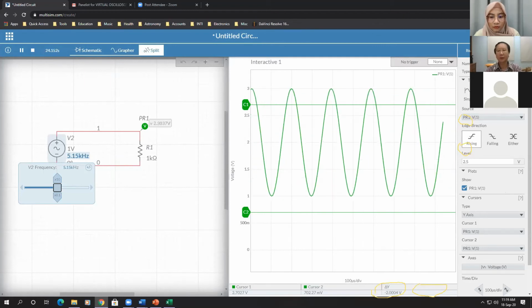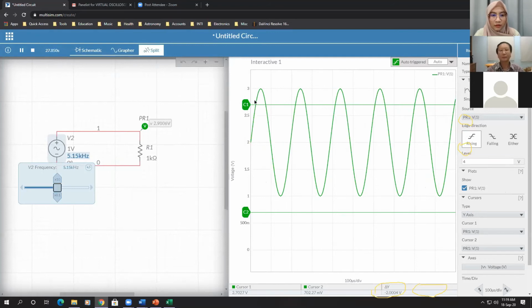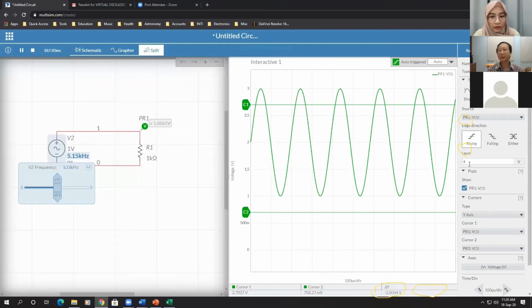You do an auto, then you set your voltage level to the right trigger voltage and it will be steady. If my voltage here is, let's say, 4 volts, and I move it out here and run it, it's already running. I think this software actually triggers automatically for you. Anyway, you need to trigger to see a nice steady waveform.